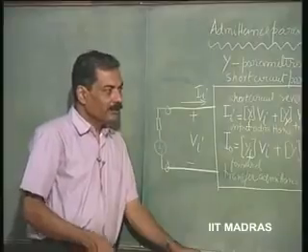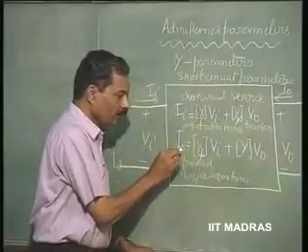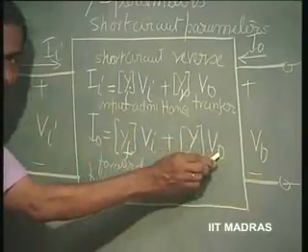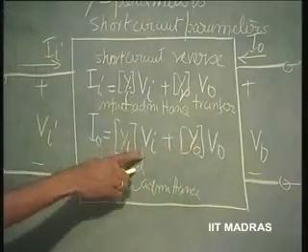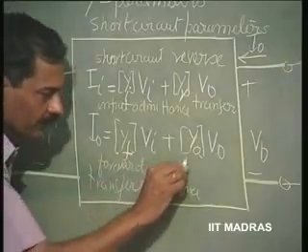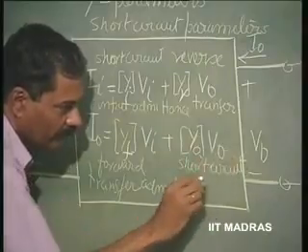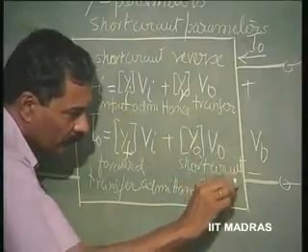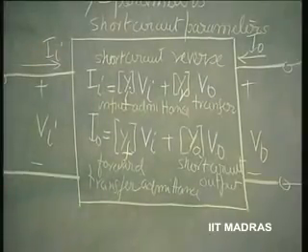We took it as conductance, here it is more general, admittance. So finally, this is output current related to output voltage. So totally output parameters, so Y0, when input is shorted. So, this is called short circuit output admittance. So, these are all short circuit parameters,